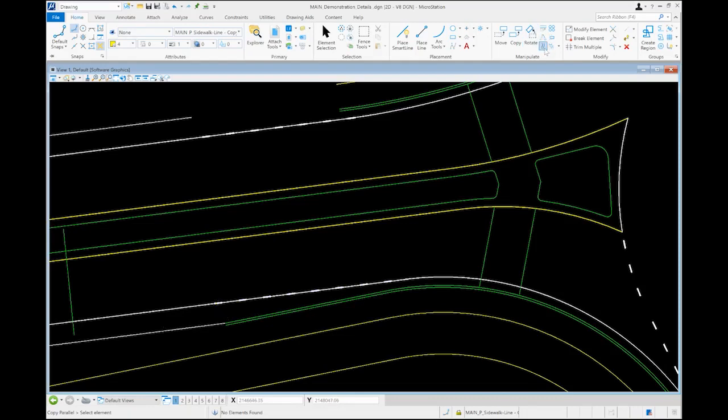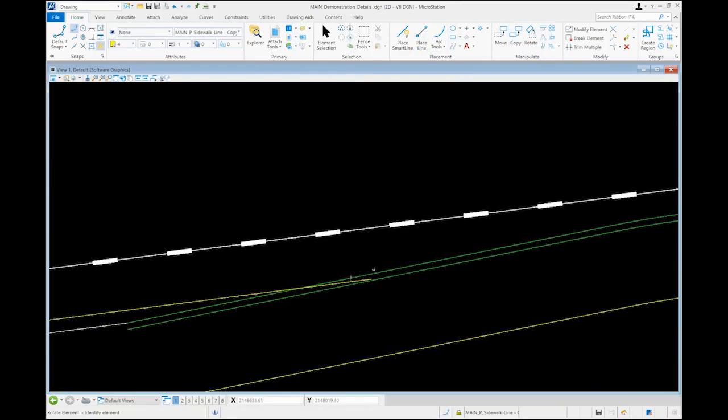So one way to do this, there's many different ways you could tackle identifying the location here, but just create an offset. I'm setting a 1-foot offset line for reference and extend that to where it intersects the curb line. And what I'm going to do is rotate the curb line 30 degrees to establish the center line of my ramp. And we're going to just put it where it's intersecting there. Let's create a copy. Try that again. So we're going to use that as the center line of our ramp.